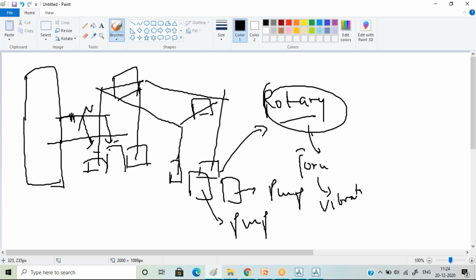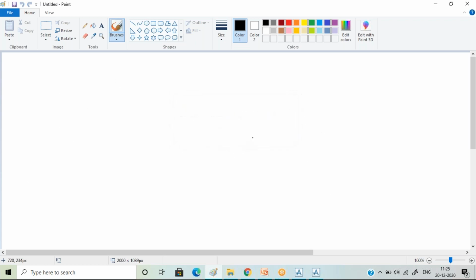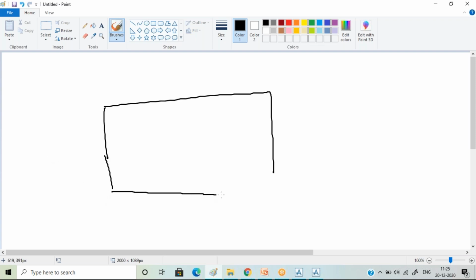So there are some prescriptions from the process team also that we have to follow, that we have to maintain this much distance. Whenever we are working on an equipment layout, we have to keep these particular things in consideration, and you'll be guided about them through the course of PDMS. Because most of the time when we are planning an equipment layout, we skip a few of the major things. It's very important that your equipment layout is such that your piping is the minimum.